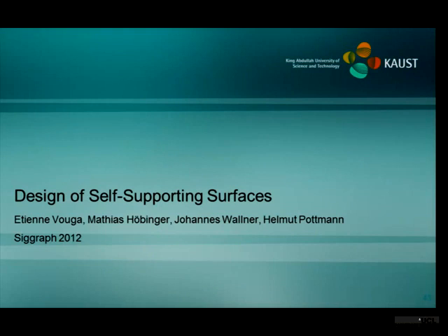So far, I have only talked about aspects of manufacturing. So I talked about flat panels, which is, of course, nice. This is always easy to manufacture. I talked about developable panels, which, depending on the material, can be good or not. So a general developable panel for glass is terrible, but for metal, it is good. But I did not talk about another important aspect, namely statics. After all, this stuff should stand, and it could be hard for the engineers to make it stand, and it could be easy. So maybe one wants to incorporate this.